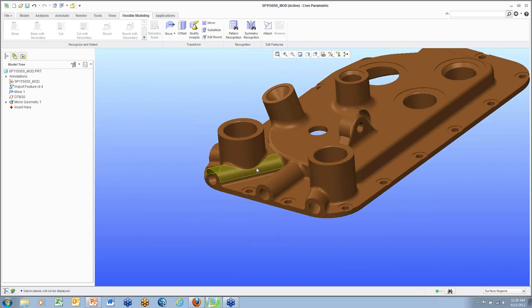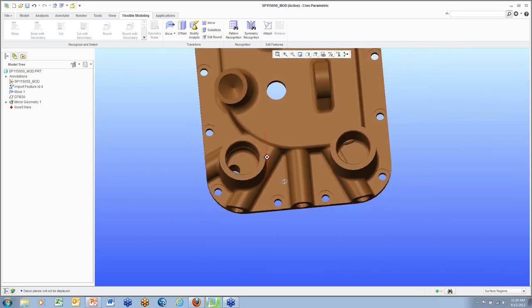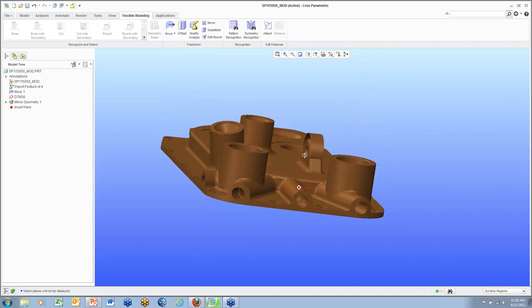I know that these look similar. If I give you a better view here, you'll note that these manifolds are in different locations. In fact, on this example here, it did have two manifolds that actually went underneath this particular feature. So yes, it does not matter what surface it is going to be mirrored onto, as long as it is mirroring about a plane. So great question, and yes, you can mirror it onto absolutely any surface you need.